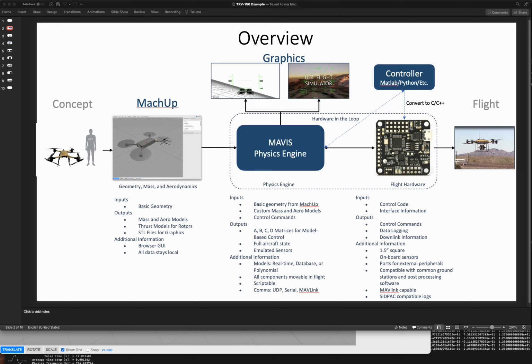And so once you have this set up, then this dashed line shows how you would have a hardware-in-the-loop simulation. And so the flight hardware, rather than getting real information from an actual pitot-probe or an IMU, is getting simulated data from the physics. And so we can test out and actually fly the hardware on the ground in simulated environments before we actually go out to flight test. And also this hardware in the loop can still be sending out visualization of the vehicle state as well.